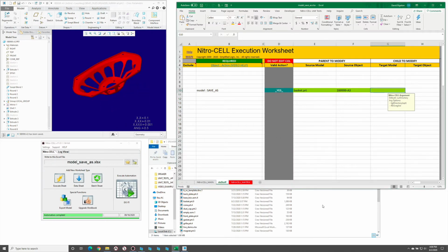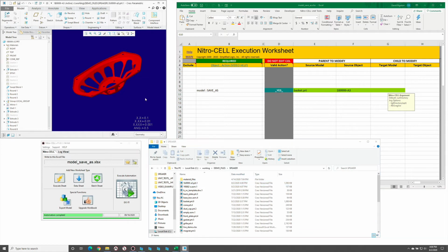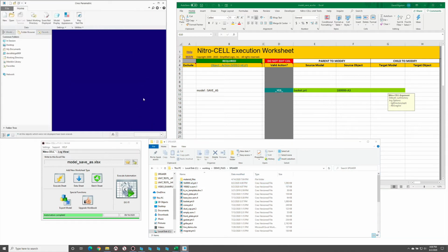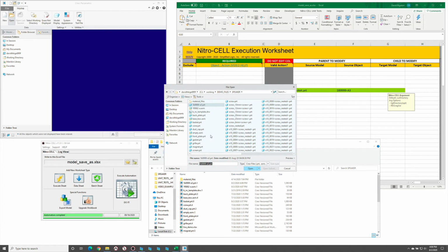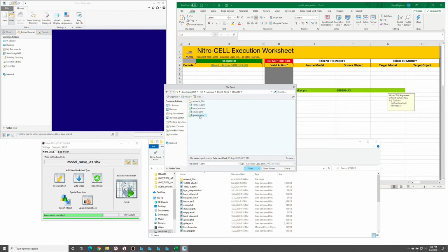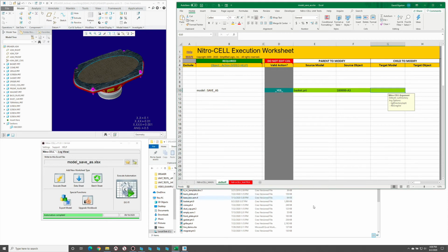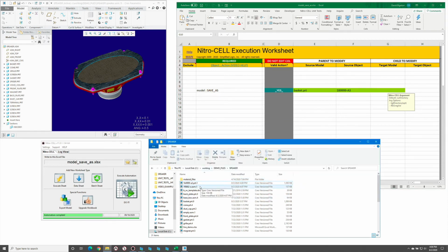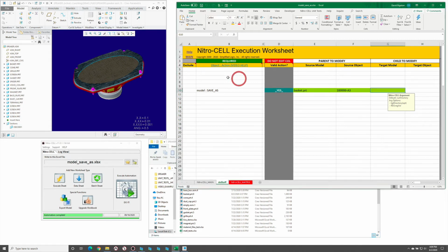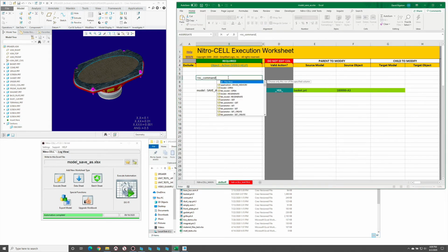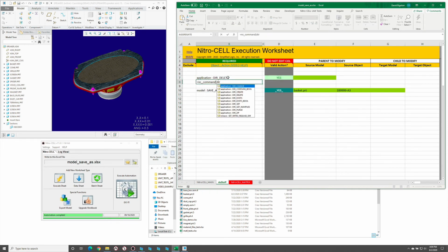This also works with drawings, but let's do something just a little bit more interesting. So I'm going to open this up again, ASM, and you can also do a save to a subdirectory too. So I'm going to delete these two files that we just generated. And because we're doing an automation, we're going to do a dir delete. And then we're going to do a dir create.